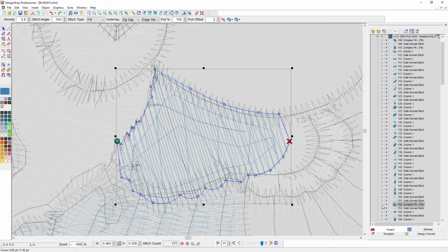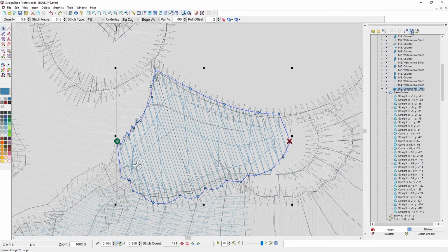If I look at them in the project view, to do this, I have to have the toggle point list on so that I can see them. I can click individual points, and as I do, you can see that they're highlighted. That's the one that I have selected. If I click it over here, you can see that it highlights here. You can do similar things. If I click on one, I can hold Shift and I can get consecutive ones. If I click on one and hold Control, I can select non-consecutive ones. So you have a lot of options for selecting those points.